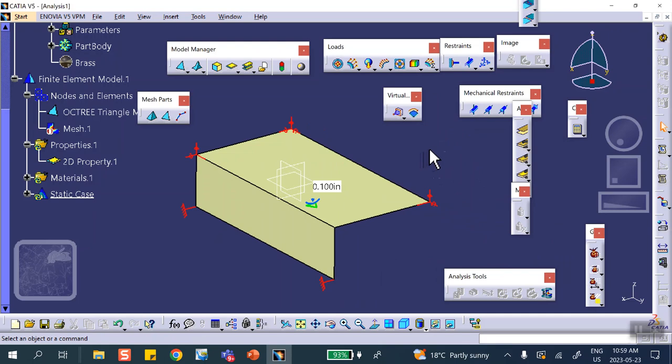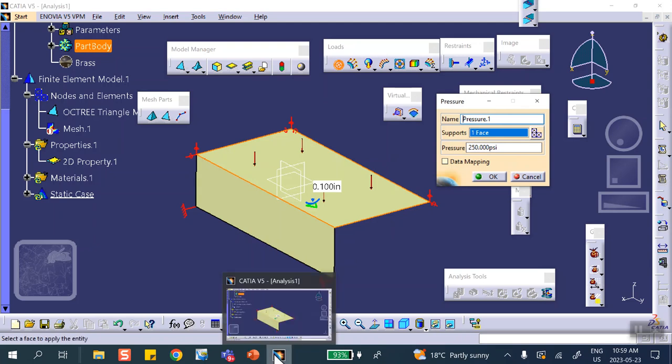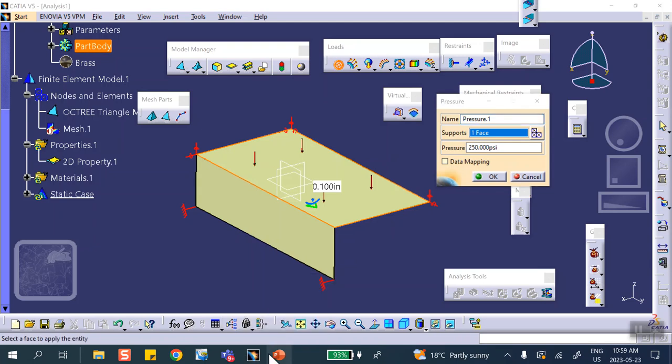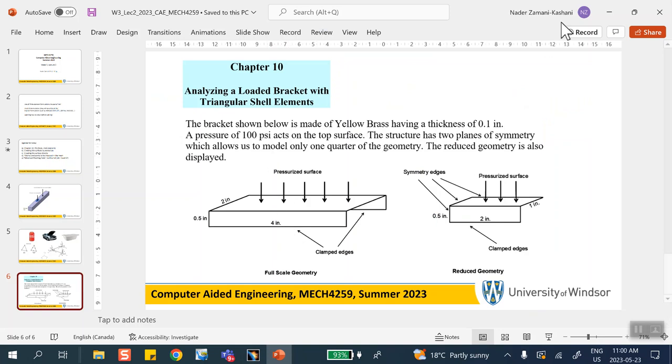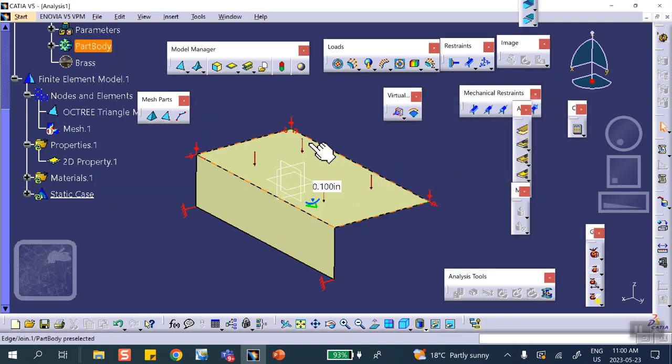Now, we have put a pressure up there, right? So we're going to put a pressure on that face of magnitude 100 psi. Please make sure you don't divide 100 psi by 4. So that's 100 psi. And if the direction doesn't look right, you just go flip it. Okay. So for example, what do I mean by flip it? You go to